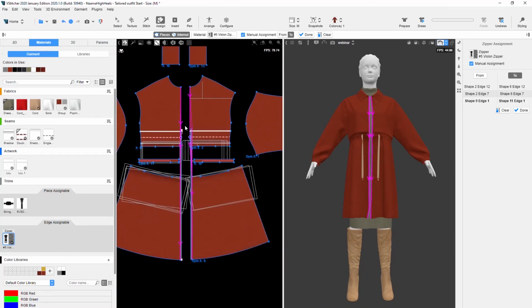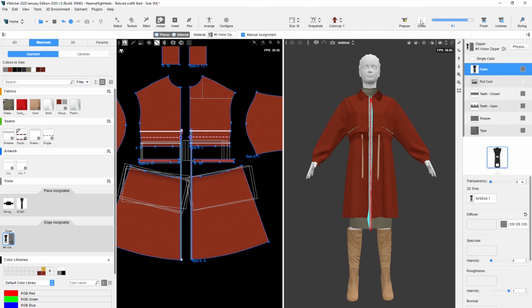Notice the manual assignment mode is available in 3 places within the interface: the horizontal context view, the right side context view, as well as the right-click menu. This garment is a great example of a use case for the manual assignment feature. It has a pleat construction coming into the center front zipper edge. With the manual control over the zipper, you can now easily skip the pleat fold.